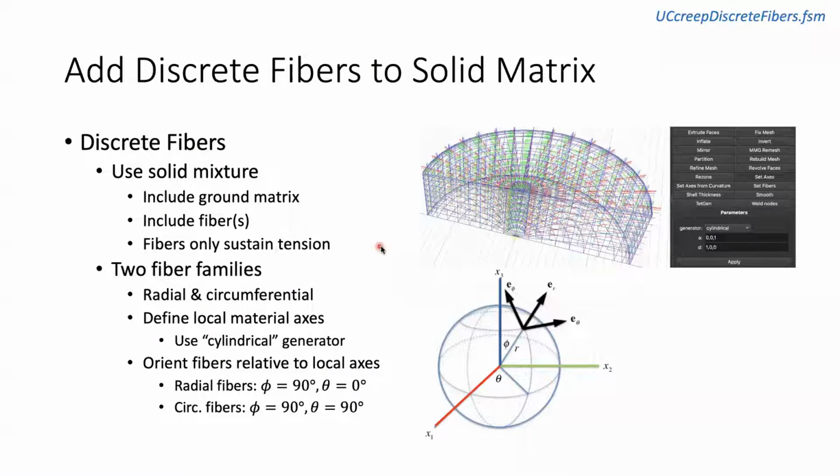families. So I want you to know that if you actually want to display the fibers, there's a plot variable that lets you specify the fiber and give it a name and the radial direction. This can be added manually because we're actually looking at the fibers within a solid matrix. And so FEBio Studio doesn't know that you're going to use a solid mixture to include fibers. So if you do, then it gives you the option to manually add this. I'm going to skip this particular detail here because it's not terribly important. You can see the fiber orientations with the material axes.